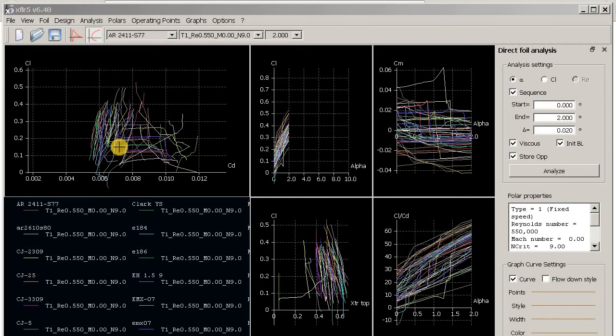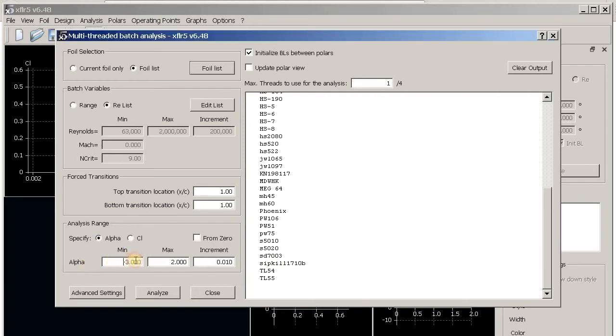And we have to do it once again, because some graphs are not starting from zero, meaning that they have positive lift at negative angles of attack. So we have to change the range to include negative alphas. And also we can reduce the range for the alpha, maybe not 2 degrees but less, because the coefficient that we need is 0.025, and here we have pretty high coefficients. So we choose the negative alpha to make sure we're going to capture the small lift coefficient, and we're ready for the analysis.